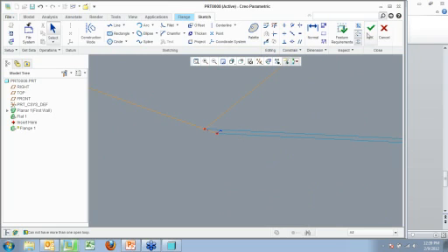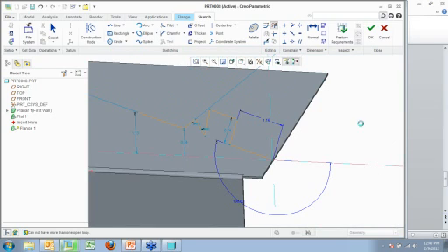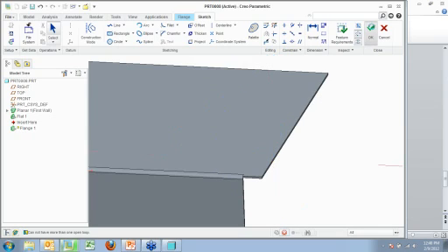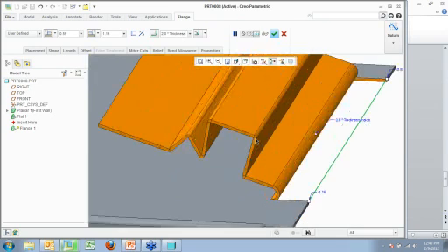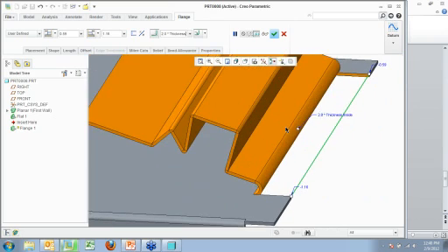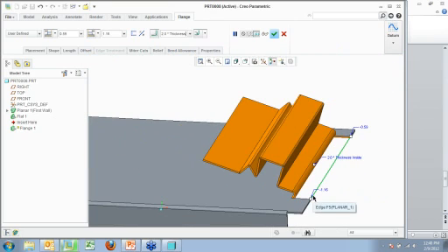See, right there, what I was talking about earlier, this highlight open ends. That's a perfect example of a time when that saved me. So come in here and I'll just trim that off. So let's say here, yeah, both the ends should be open. Now see that crazy wall I just generated? I can go in here and specify I want it to be 2 times thickness for all these bends, so I have to actually go in there and change those individually, it looks like. But this is something that a novice with sheet metal was able to create in 30 seconds of playing around.